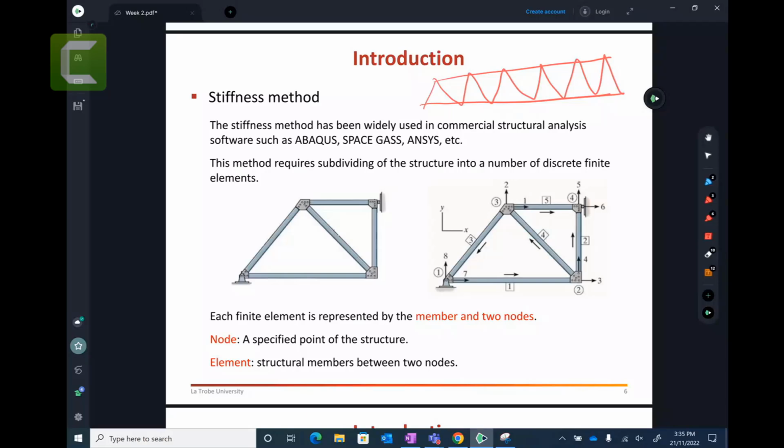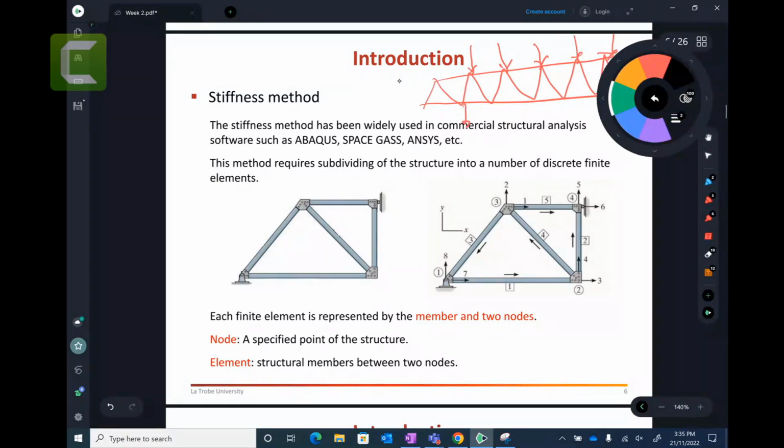The main philosophy of the truss is that it has joints, and the loads are only applied to the joints. You can see the loads, and you will never get these ones. No, that is wrong. The truss will not get any load coming onto the members, right? So that green one is wrong. The beauty of this truss is that the loads are only acting at the joints, which is a good part. That is the one philosophy.